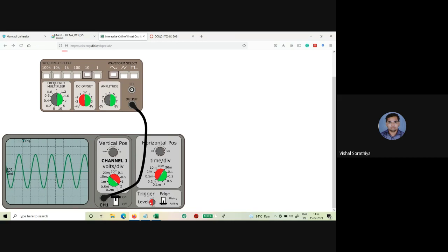Is it okay, triggering? Sir, meaning from 0 to 4, wherever we keep it, it will be the same, right? Like it is going to be in a steady manner. Yes, it is going to be steady. There is a little bit of shifting. Why is there a little bit of shifting? Say your triggering signal starts at 3. If you change this trigger value from higher to lower, the triggering point changes and your signal gets a little bit shifted from the original axis, but it will make it steady.